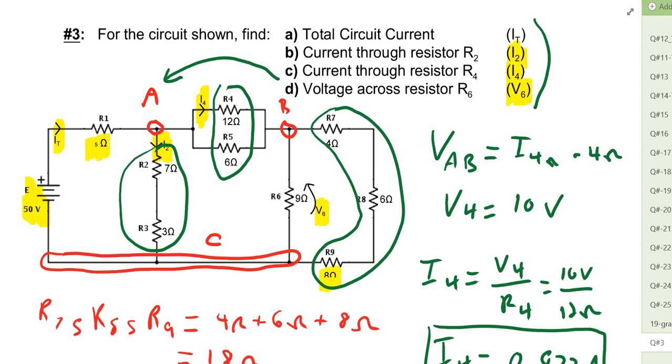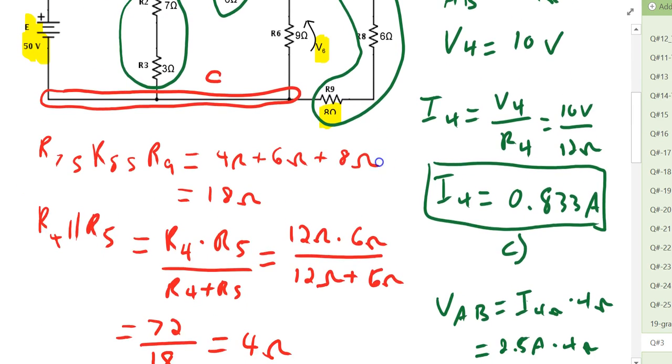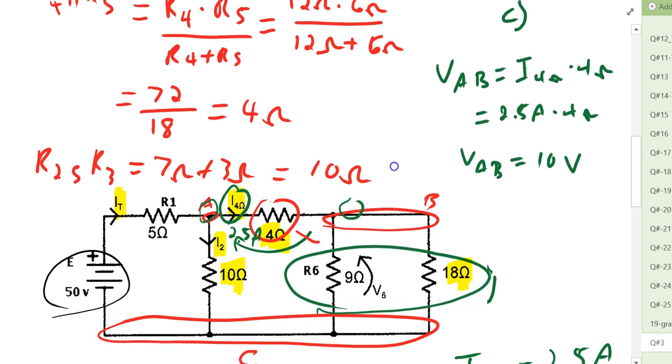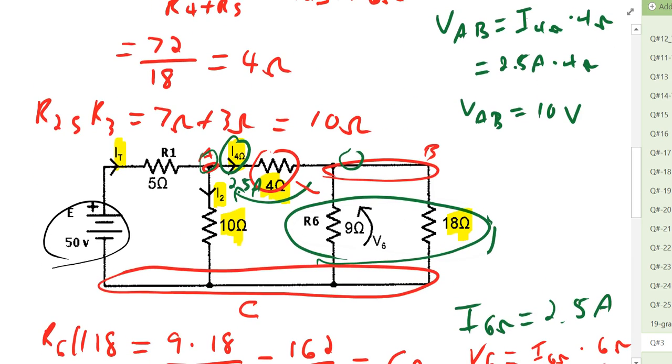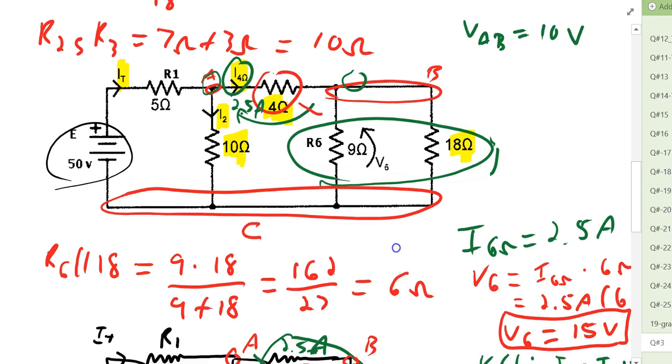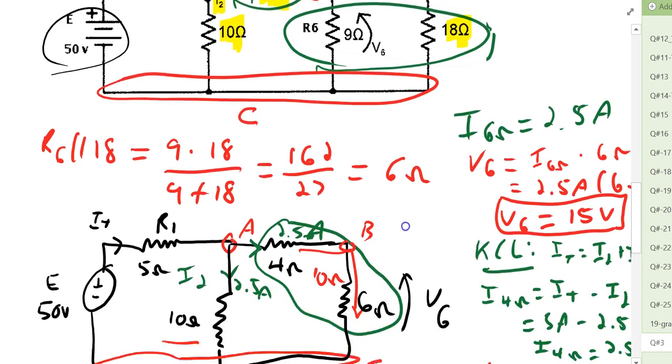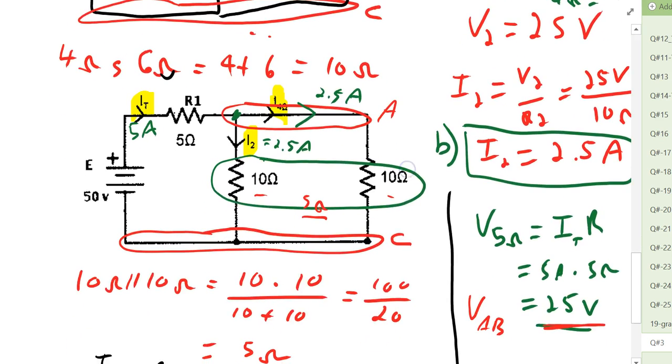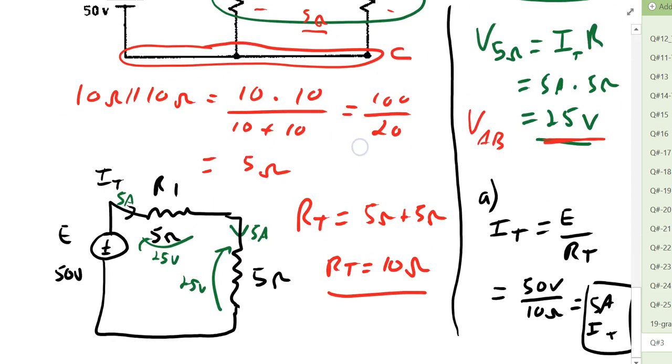Very often, start at the right side of the circuit, work your way back to the source. Then, as we complete the calculations, we identify the equivalent resistance values, we redraw the circuit until we have simplified it to the point where we have calculated the total resistance in the circuit, and in this case, of course, 10 ohms.